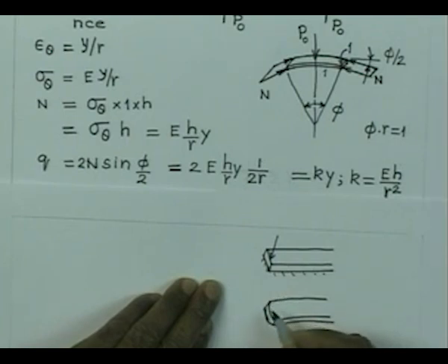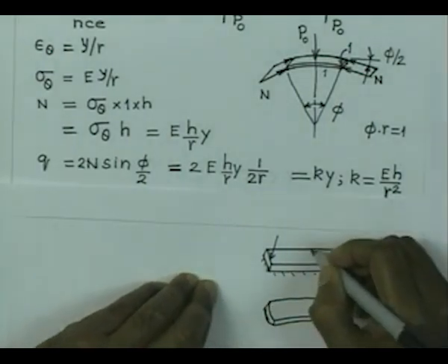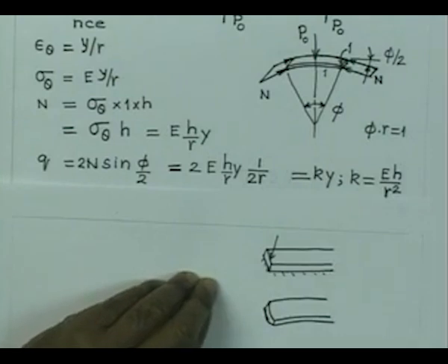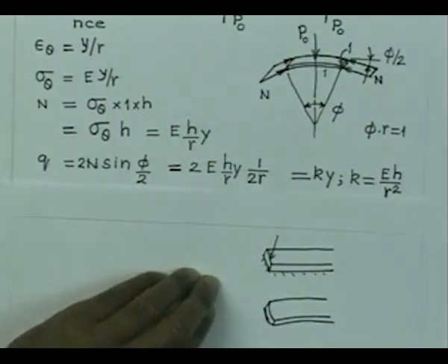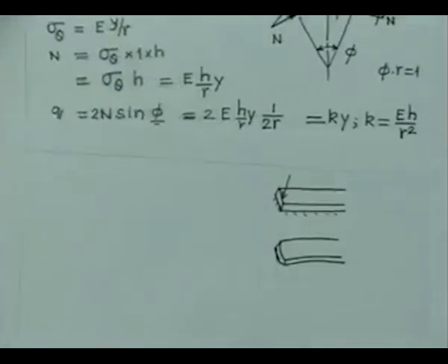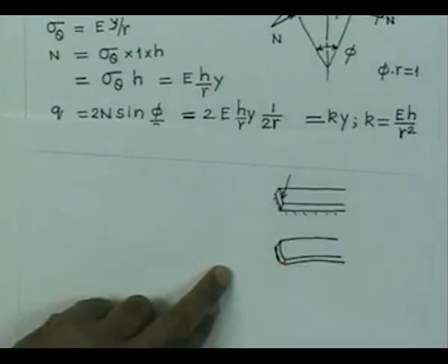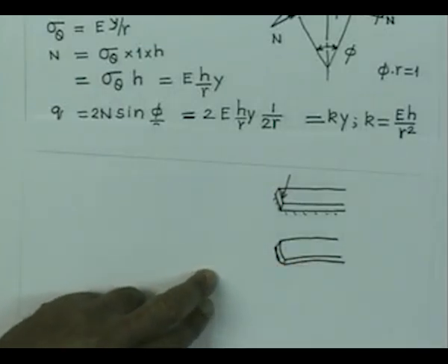This anticlastic curvature can come up when the beam just has a finite width dimension, but in the case of the cylindrical cell, this sort of curvature cannot take place freely, and therefore there is extra resistance.